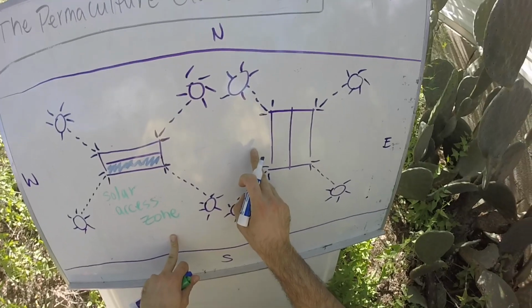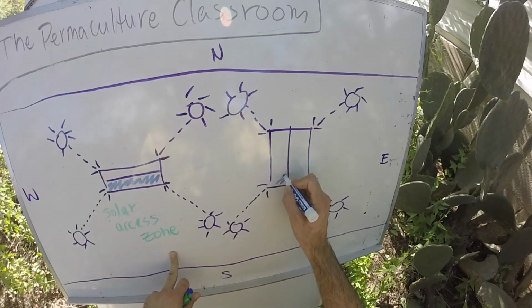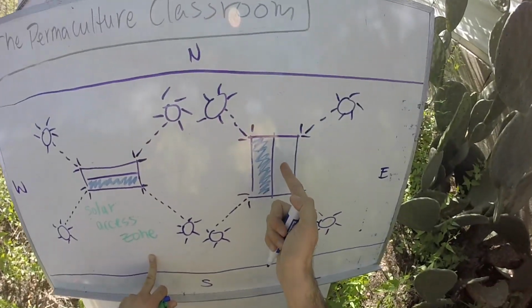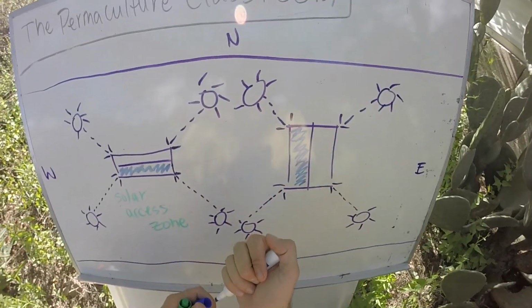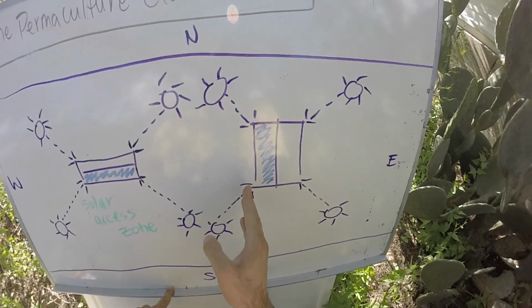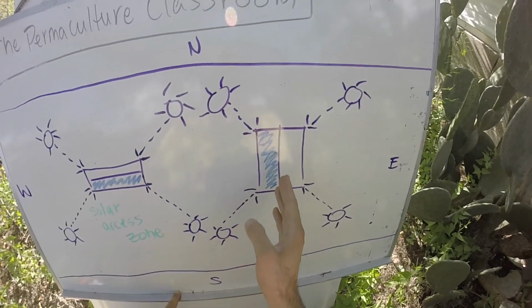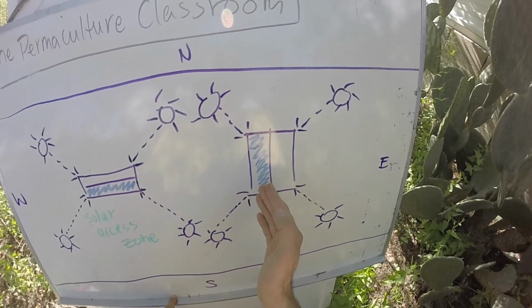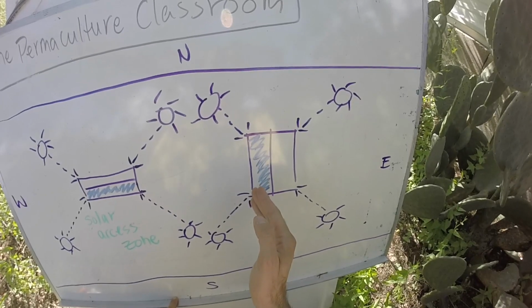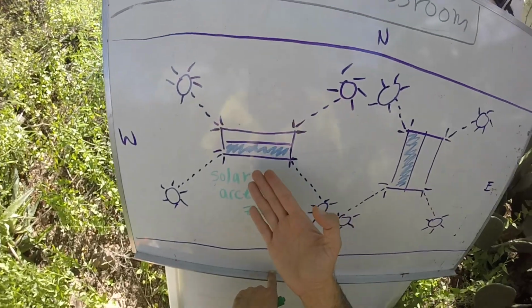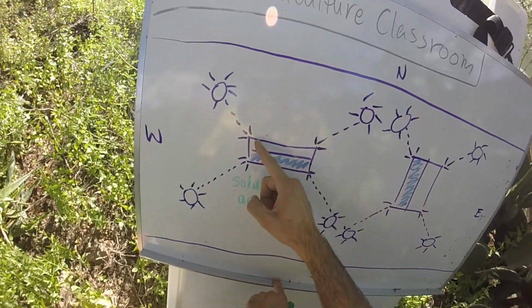So now let's talk about the north-south orientation and what happens here. So in the summer, we're actually doing what we're doing in the winter on the east-west orientation. We are harvesting the sun in the summer. We're going to heat up half of our house basically from noon until sunset with the summer sun. And it's going to be super, super hard to cool our home passively.